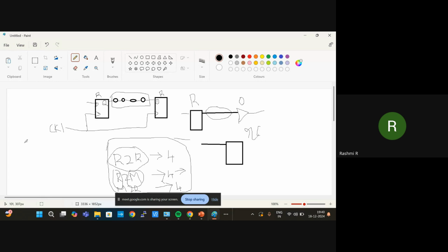What it will contain is the start point. Let us take a reg to reg path group: start point as register, end point as register, with which clock it is getting violated, and from start point to end point, what cells are present in between.